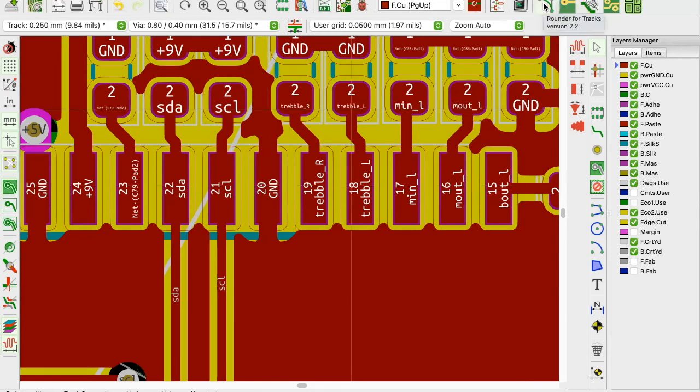Important to note here, the color that you select for your solder mask really affects the sizes. You find that with some fab houses, not all colors have the same clearance. We had an issue when we were using white because they needed a bigger clearance. I remember it was 0.22 mm.